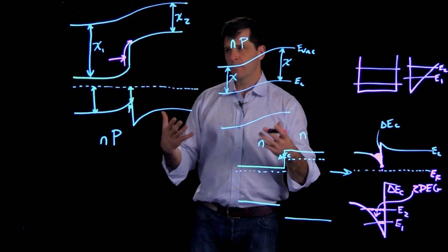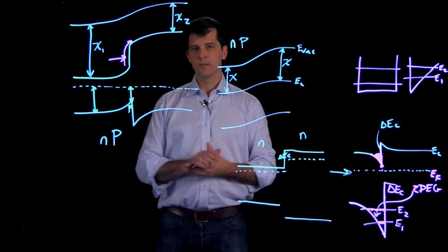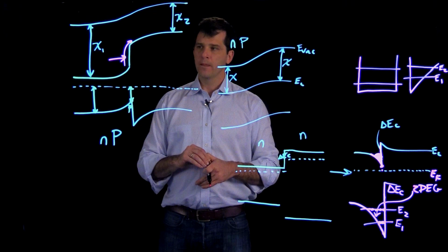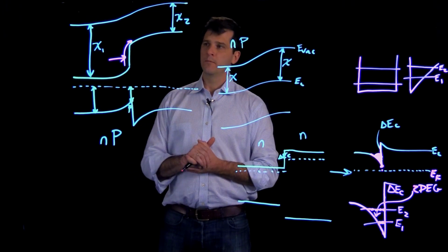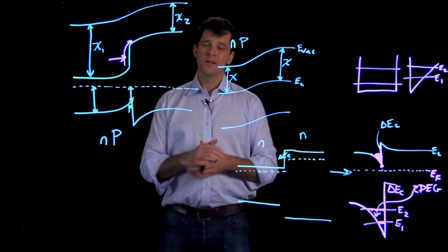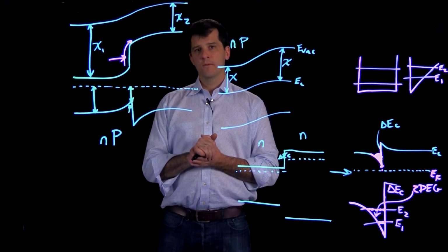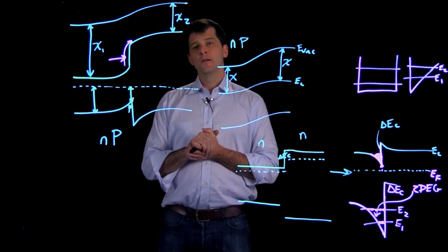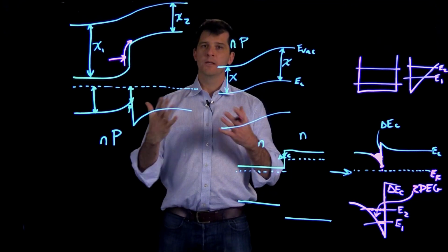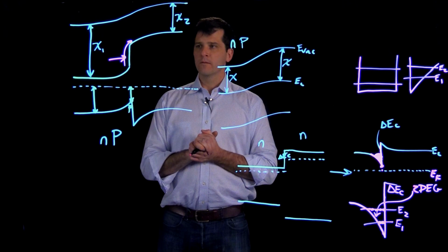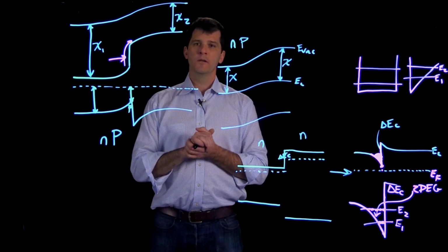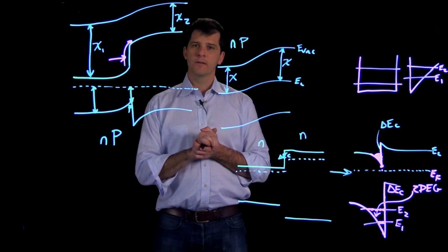However, it turns out that also drift and diffusion have to be included. So the treatment is quite advanced and not given in most introductory textbooks. So we won't worry about it too much here, except to say that they'll still behave as ideal diode forms, but the details of what goes into the J0 is more complex. So that'll wrap up our discussion of semiconductor heterojunctions for today.